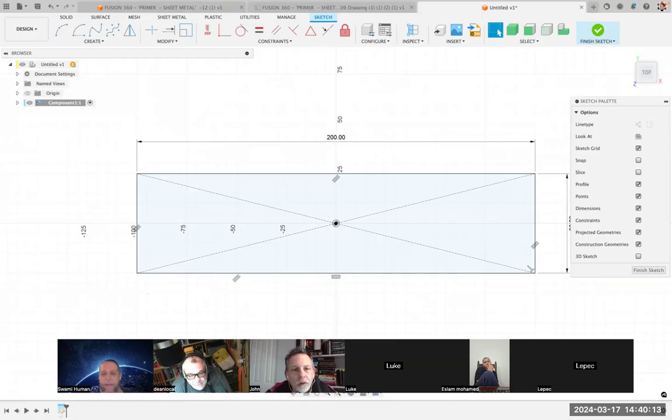All right, so we're going to make a line on the right side here, maybe L for line. If you hover over the top line, it will find it with a little blue X somewhere over here. If you click, it'll lock onto it. Come straight down till you find the bottom line. You'll see a little blue square there for perpendicular, and click again. You still have the tool, hit enter to get rid of that. So now we're back to the picker, and we have our line, and it's constrained to the lines of the rectangle, but it can still move left and right. We need to lock that down.